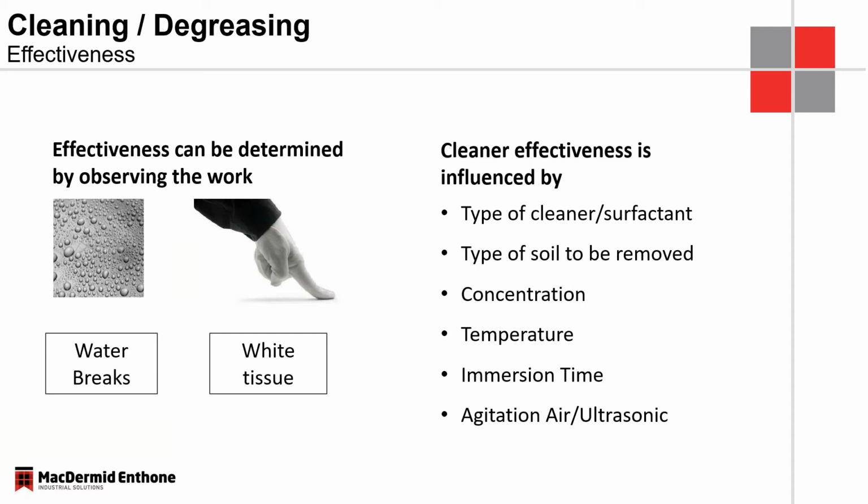We can increase the concentration up to a reasonable high limit before we see any etching on the components, or before we actually go so high that the surfactants will oil out of a solution. Temperature, again, the higher the temperature, the better, but we are limited with the attack on the aluminum surface here. So normally 65 degrees Celsius is a good benchmark for cleaners.